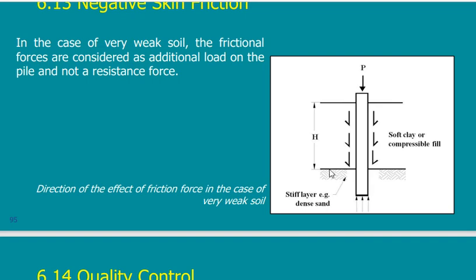It will settle, this small layer, carrying all that is above it down. So it will change everything. So it is very important that you conduct a very good site investigation to see all layers, because if you have a minor layer that is soft clay, even if it is followed by stronger layers, this soft clay will change all that is above to negative skin friction.